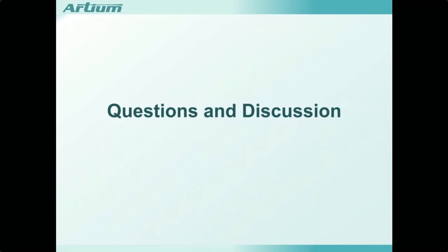But again, it comes down to if you're sampling at a uniform rate, then you must meet the Nyquist criteria. But if you're random sampling, you're not going to get aliasing. So if you sample for a long enough record, you can then come back and use that information to resolve relatively high frequencies in the flow.